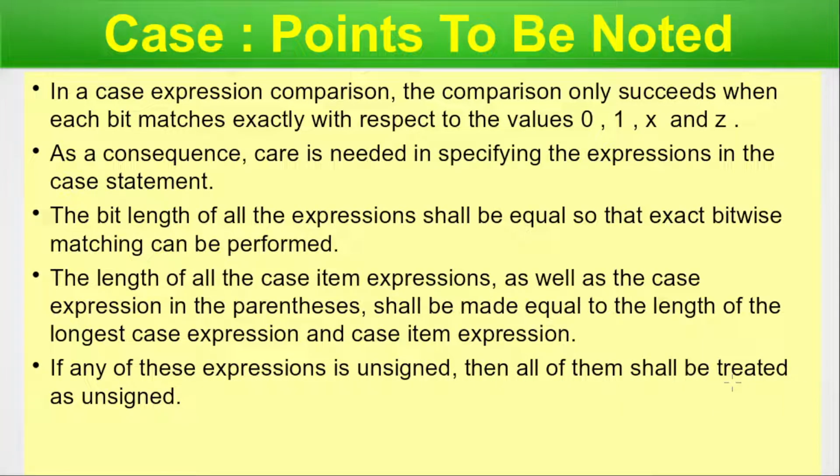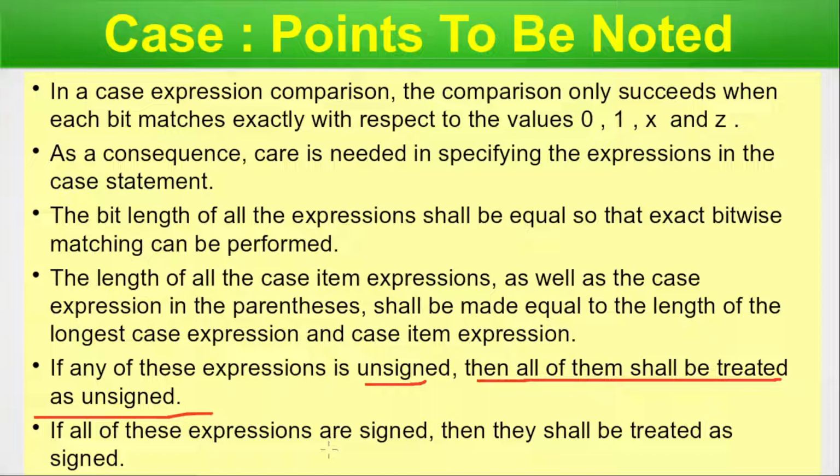If any of these expressions is unsigned, all of them shall be treated as unsigned. If any of the expressions are signed, then all of them should be treated as signed. So you have to be very careful. Apart from the width, you must be careful whether it is unsigned or signed. You have to stay in the same convention, either the signed one or the unsigned one, whatever is applicable. It's not your choice.